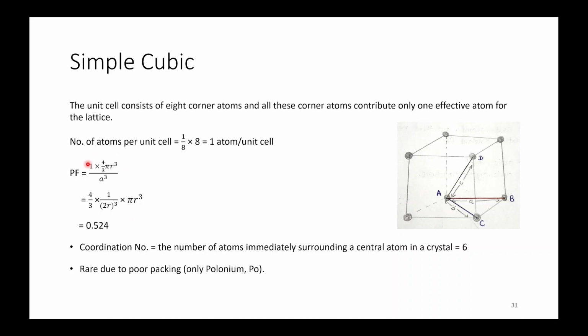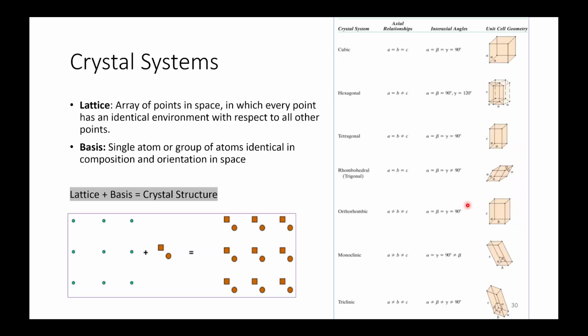He has asked in that question about cubic. Cubic meant that these lattice parameters will be equal. For example, in this cubic system A, B, C, these are all equal. So all your systems BCC, FCC and simple cubic, these three are based on this cubic system. These all will be having these lattice parameters equal. That's what that part meant.